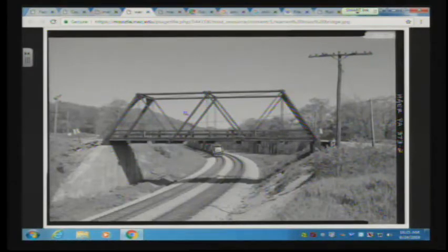If we thought that the most load that this structural member would ever take would be 1,000 pounds, we would want to build it with a structural member that would take 2,500 pounds. So we usually use what's called a factor of safety of 2.5. We come up with everything we could think of, every reasonable thing that would increase the load on the structural member, and we multiply it by some number that's dictated by our profession. But generally 2.5 is a good number.